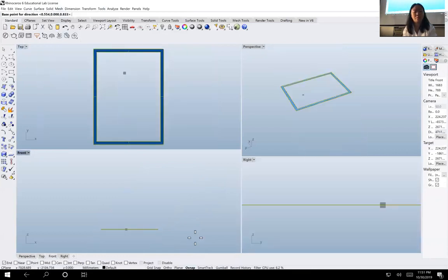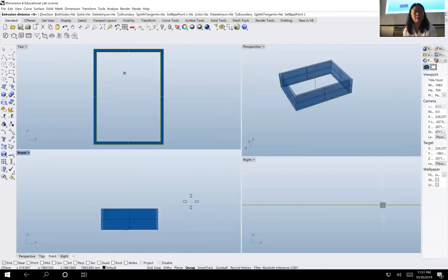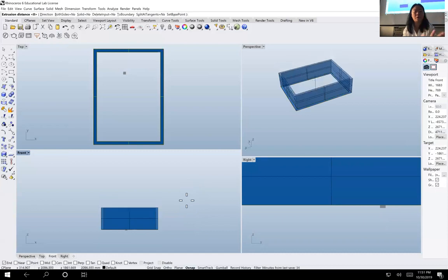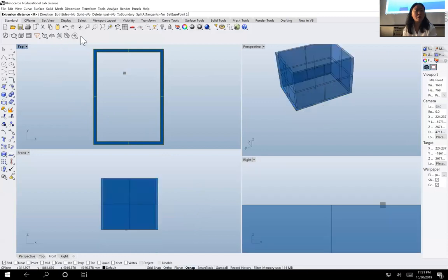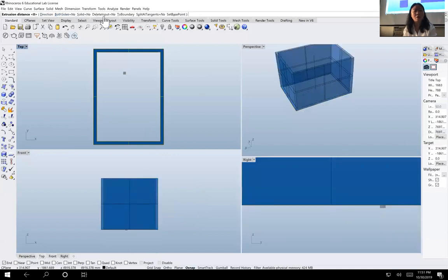So I'm going to bring it back and press shift. Okay, so it's still hard, I mean, vertical. I'm not extruding diagonally. So you have many options when you look at all of these options here. For solid, I should say yes here, because once I extrude, I'm extruding into a solid piece. So here I should click and change it to yes. I'm not reading all of this, and we're just going to give a height.